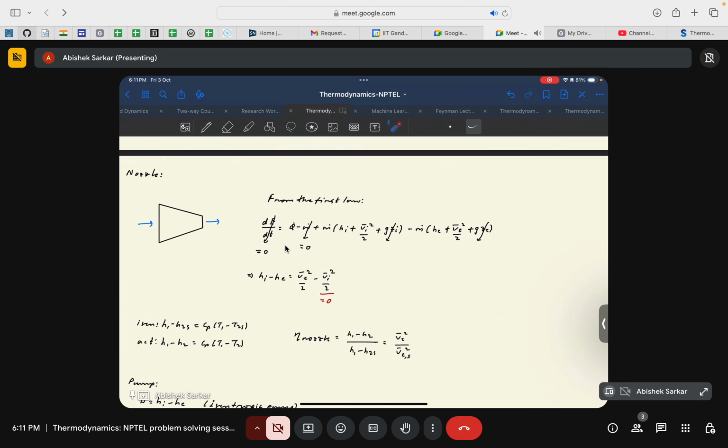But some viewers, students or even professors attending the sessions may be critical about using these terms because of the concepts on which these nozzles and devices work. That is, a nozzle increasing the velocity of the fluid is only valid within the subsonic regime. If the flow becomes supersonic, then it works as a diffuser.